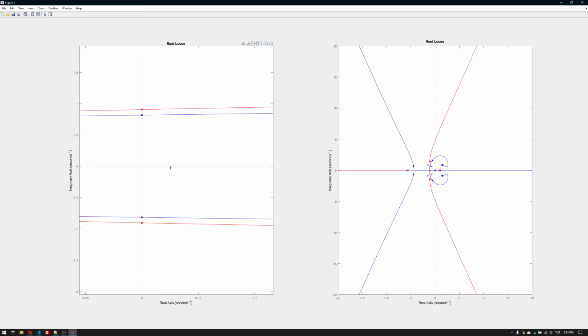And you can see that the omega value, or the j omega crossing coordinate here, is changing, whereas the structure of the root locus is also changing. So if you increase the order, you should get a tighter bound, but due to the crossing not being on the origin, it will produce some faulty results.